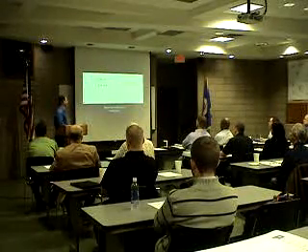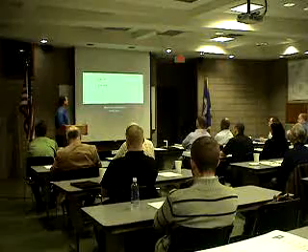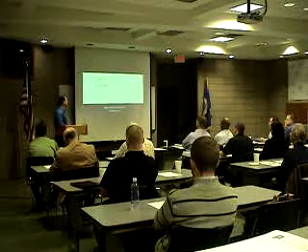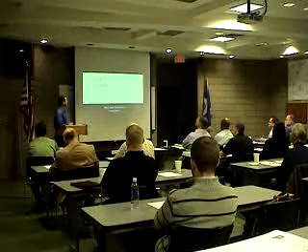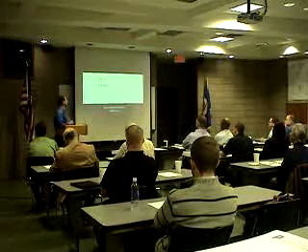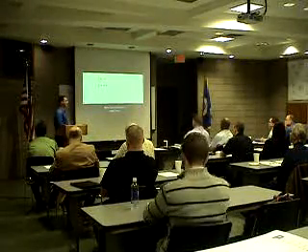And these are our island cubes that were in the main open office. And each one of these just has a three-phase junction box coming out of the floor, or 3 poles, and you'll basically be coming out of this junction box with a snake and running it through the cubes.